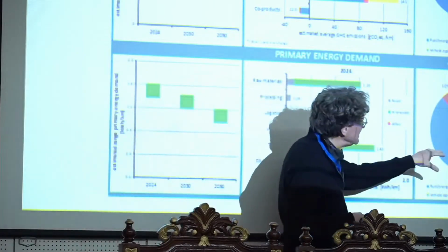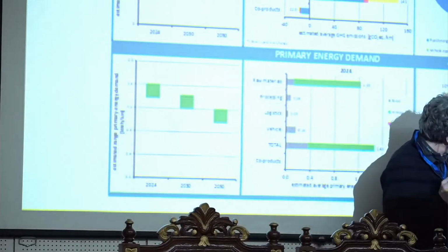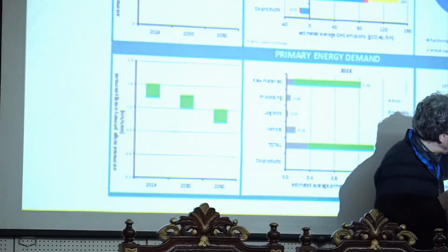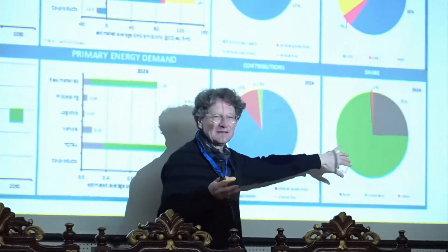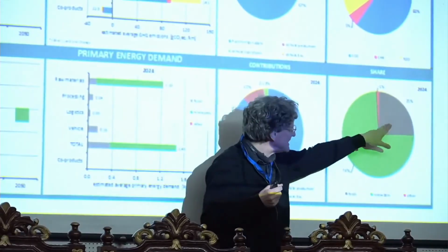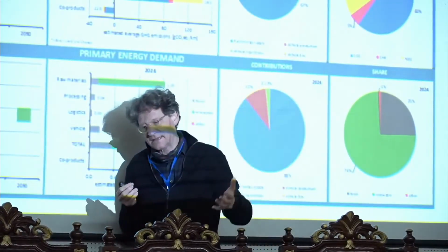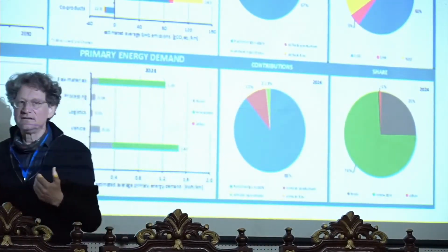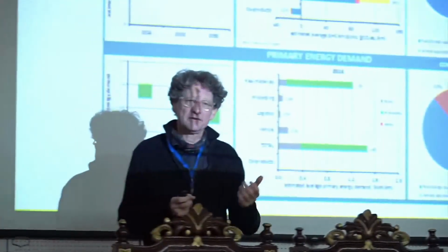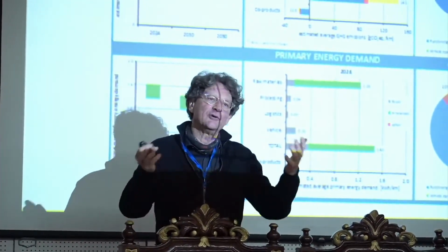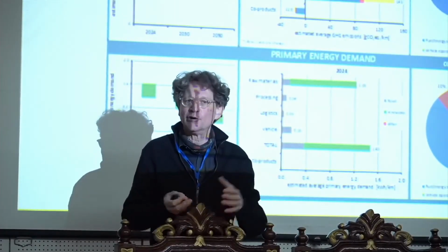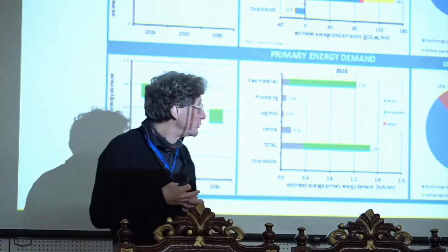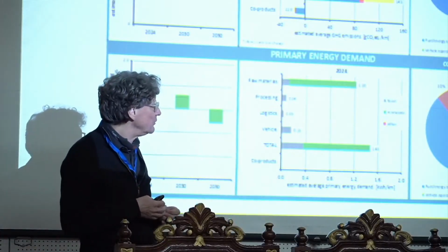But you also see that for the biodiesel, the share of renewables is nearly three quarters. So this is a little bit higher than for the bioethanol because the energy demand of making biodiesel and the electricity demand is much lower compared to bioethanol. Because in bioethanol we need the distillation of the pure alcohol, and that really needs energy to evaporate and get rid of all the water.